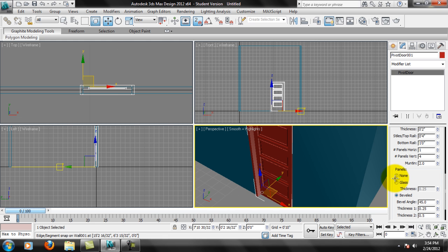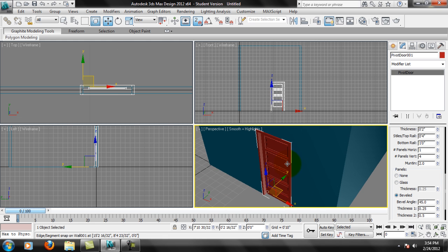So this is the upside to working with walls, being able to use these doors. Now, can you use these doors with other things like just standard boxes? The answer is yes, but you need to create, remember, a Boolean or something to create the opening the exact size that you need, by using the snaps and by using the AEC geometry. And remember, this door will only work with this wall. When I say that, I mean automatic cut. It will cut through the wall automatically if it's an AEC wall and an AEC door. If this was a box, we would have to use a Boolean to hollow out that shape and then place the door in there manually and make sure everything fits right. So the advantage of using walls is actually using the doors and windows.